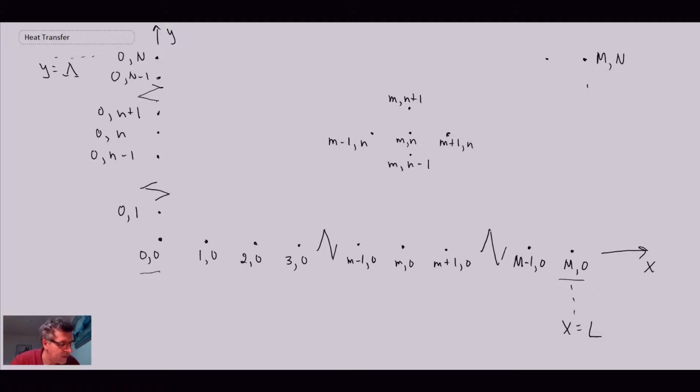And what we're going to do is focus in on 5 nodes in the middle of our object. Specifically, what we're interested in is the temperature at node Tm,n, and that is at some point within our object. We're going to be writing out the finite difference form of the heat diffusion equation with the purpose of isolating and determining what Tm,n is.